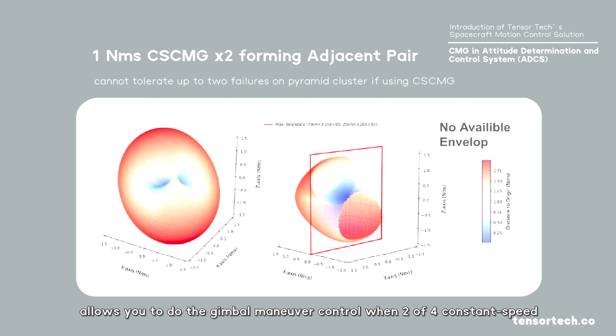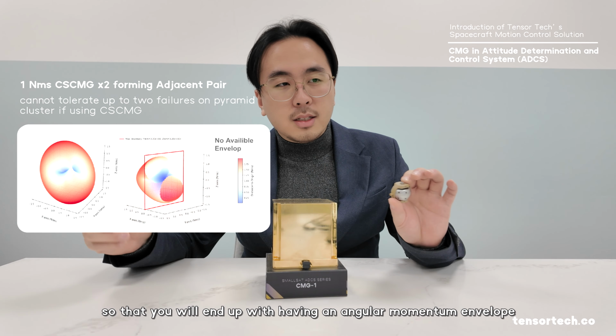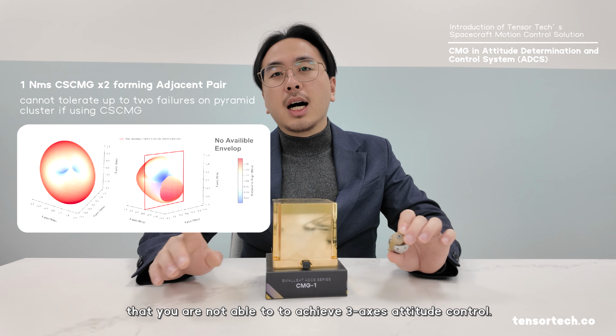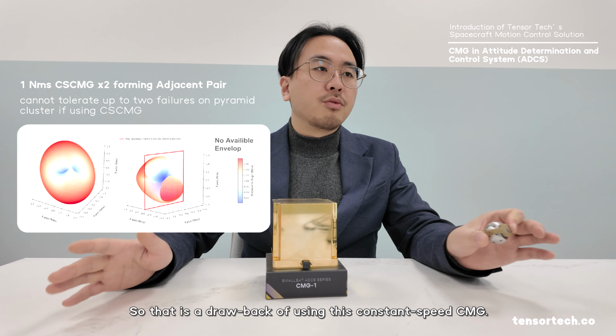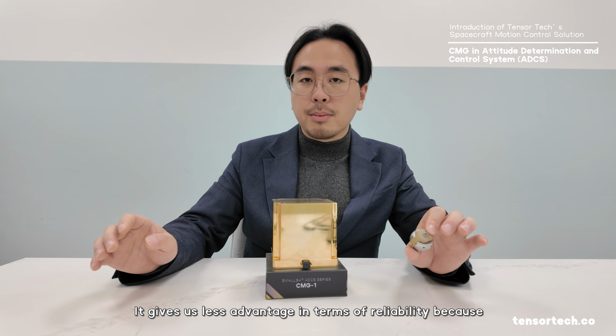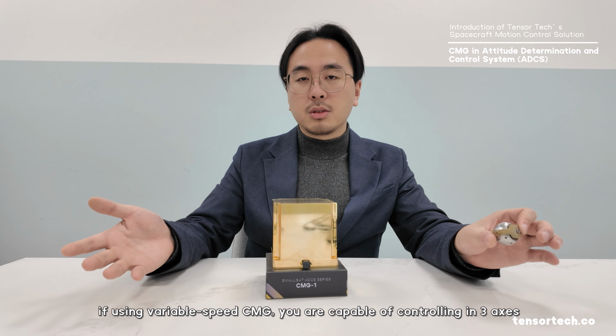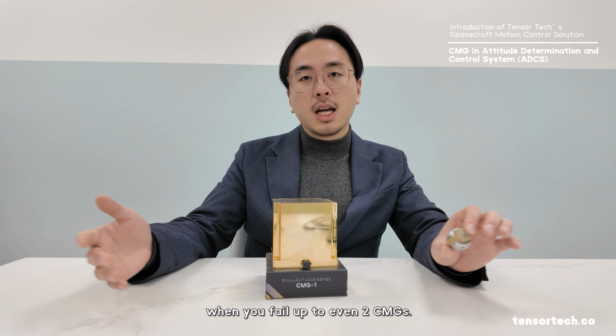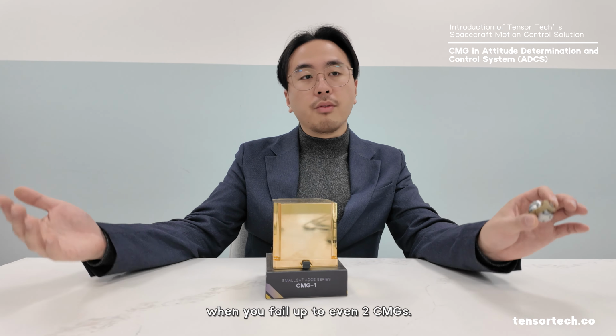When 2 of the 4 constant speed CMGs fail, you are not able to get a valid angular momentum envelope, so you will end up not being able to achieve 3-axis attitude control. So that is a drawback of using constant speed CMGs, that it gives less advantage in terms of reliability, because with variable speed CMGs you are capable of controlling in 3 axes even when 2 CMGs fail.